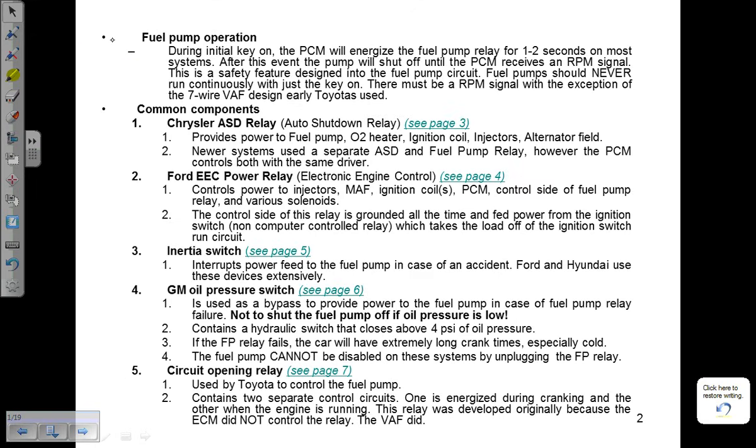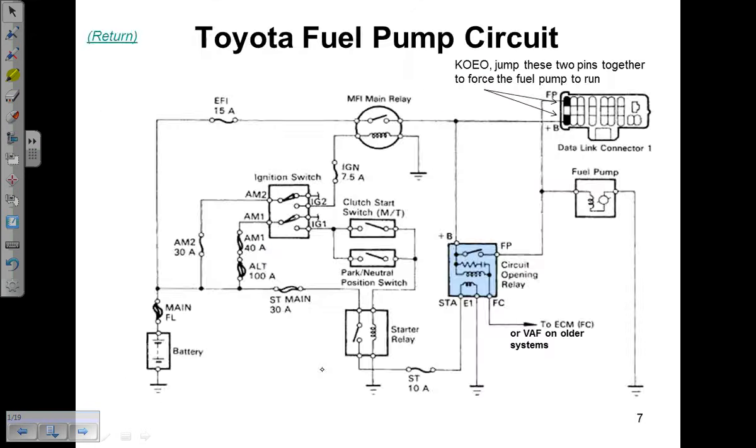All right, let's look at another one. The circuit opening relay that Toyota uses. The only reason I pulled it up again is just to show you guys what we can do with energizing pump circuits. And this is a Toyota design, and I'm pointing these out in the picture on the data link connector under the hood. And I don't know if they still use this in the OBD2 cars, 96 and newer or not. I think they did.